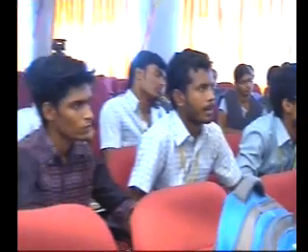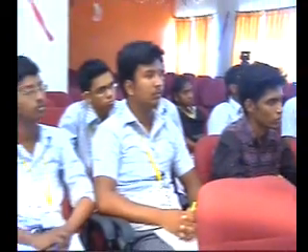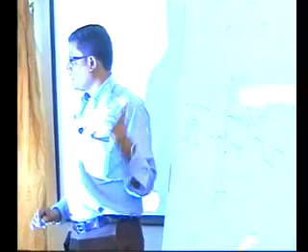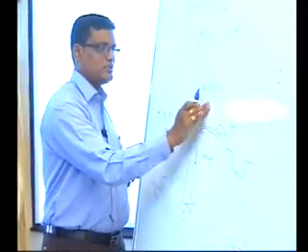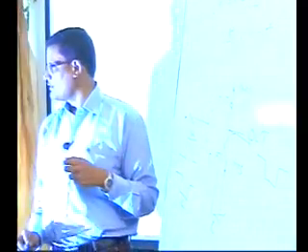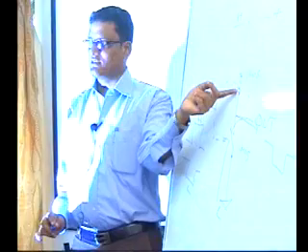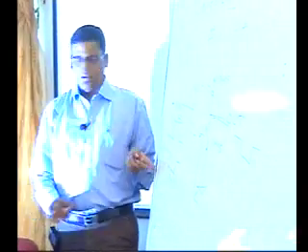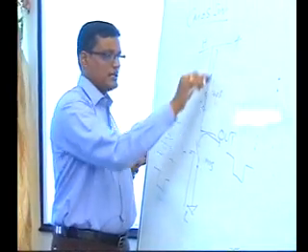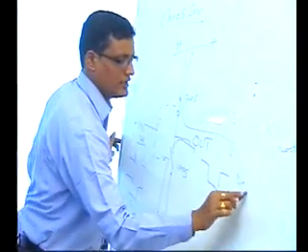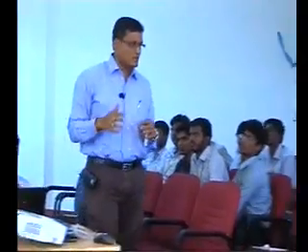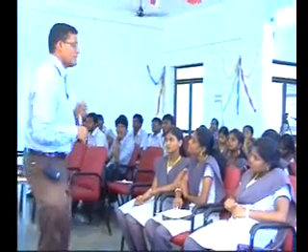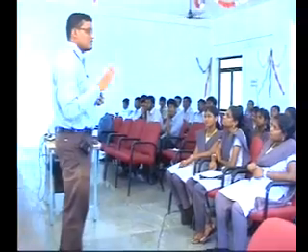When this is closed, what is the voltage? This is a low value, by the inverting action. When that is open, this will be closed, because the PMOS transistor is active for lower voltages. In this case, the high value will come here. So you will get this. Whether PMOS or NMOS, whatever logic you are talking about, basically transistors work like switches.